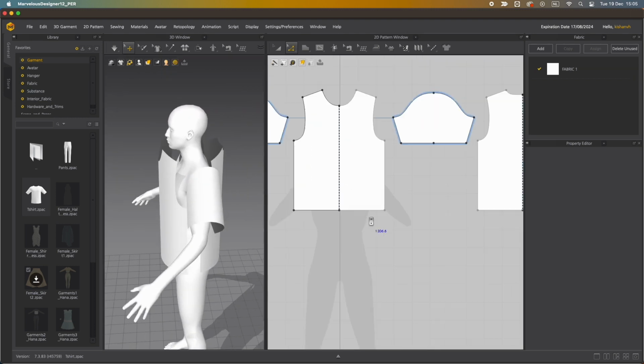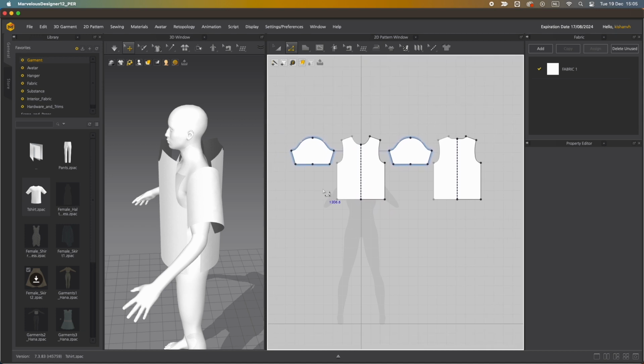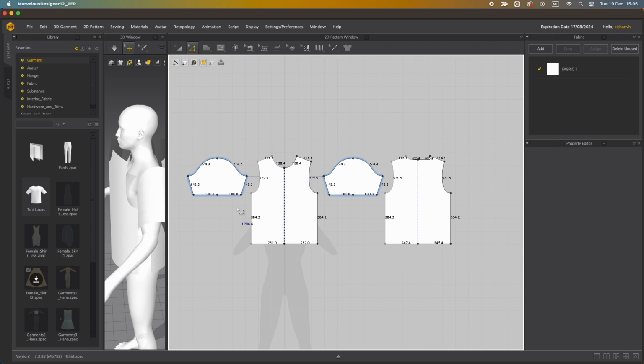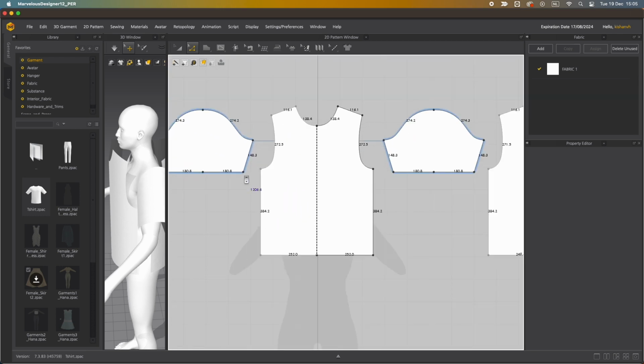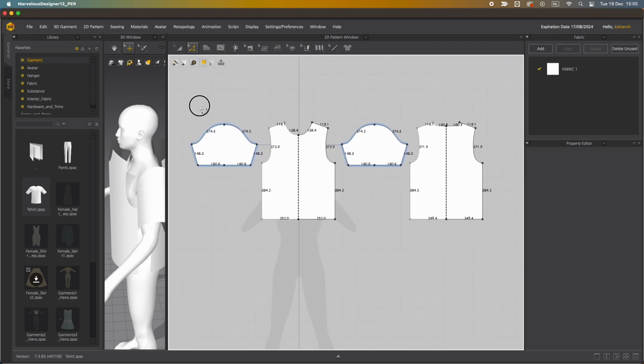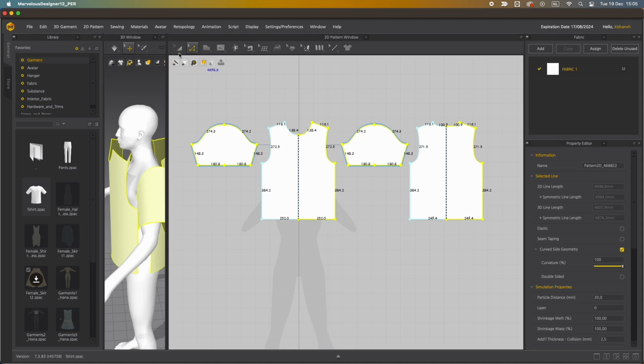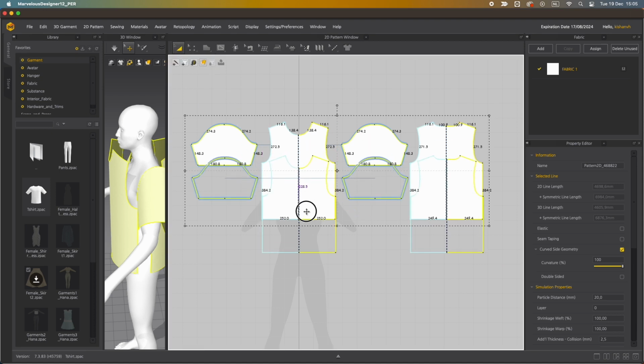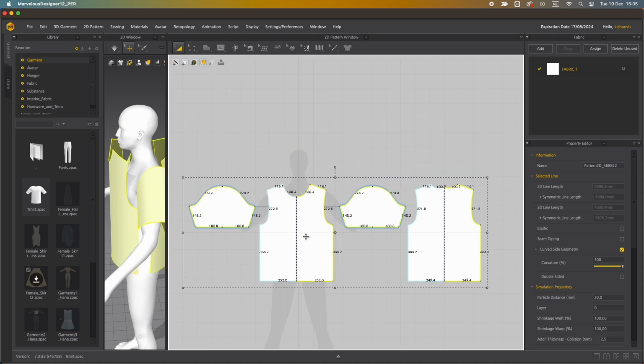Deselect arrangement points. In the 2D view, make sure they cover the torso area. Press Shift+Z for a quick overview of the size lines in your design. Select the Transform Pattern command and choose all shapes to arrange and cover the torso area.